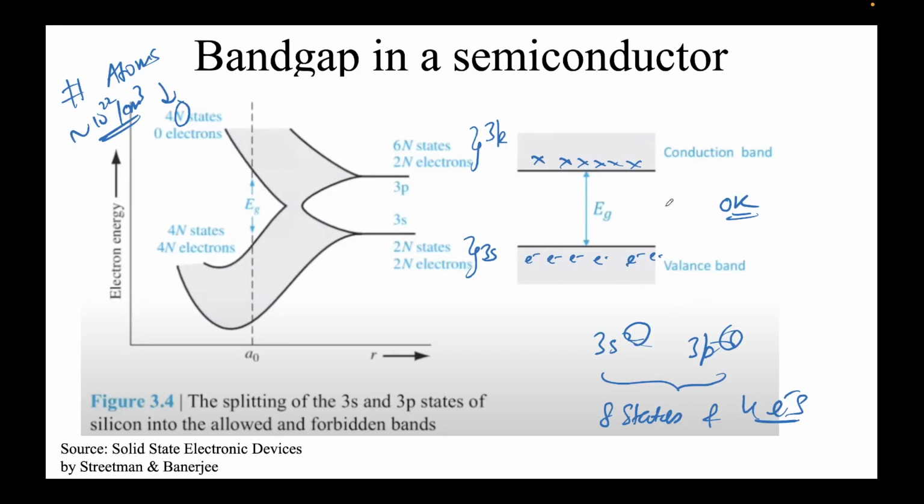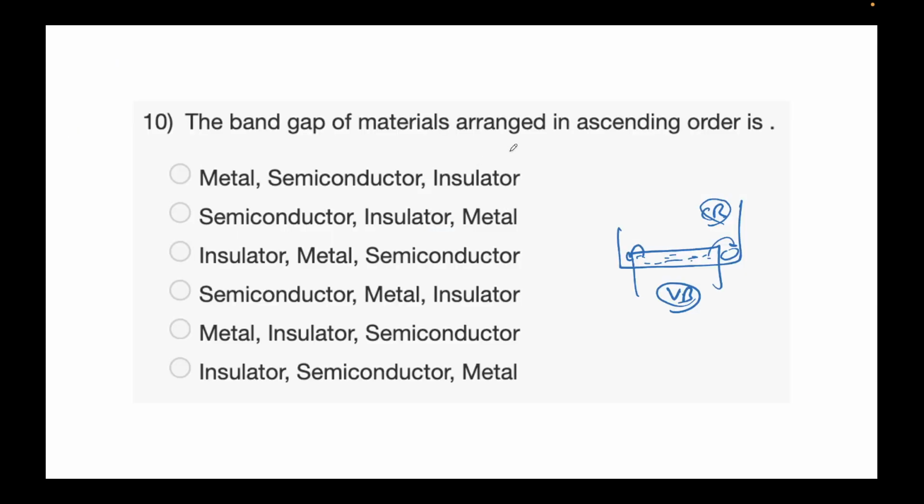In semiconductors, this is the case. In insulators, this Eg is huge, like 8, 10, or 12 electron volts. For silicon dioxide, which is an insulator, I think it's around 9 electron volts. Hence, this is an insulator. Semiconductors, you can say, range from 0 to maybe 6 or 4. That depends on the definition actually. Some people draw the line at 8, some at 6. Metal has 0.